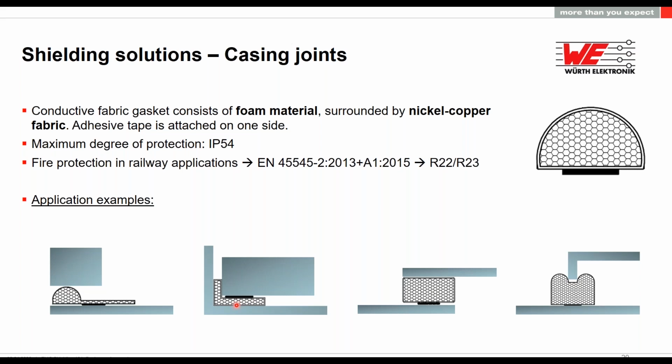So at the end, we ensure that the housing has continuity through the cable. I would say this is the most common way. There are, of course, some filters for HDMI, but normally the first solution is to use this one because it's much cheaper. Implementing a filter would be more expensive.